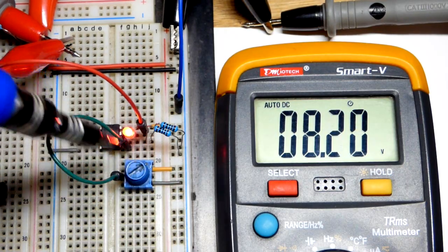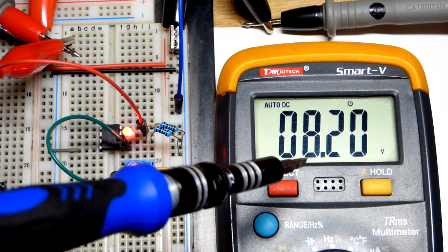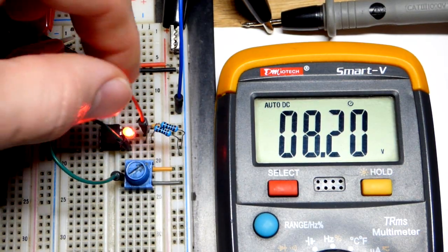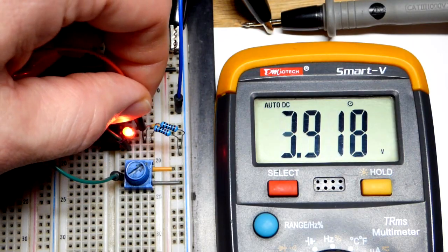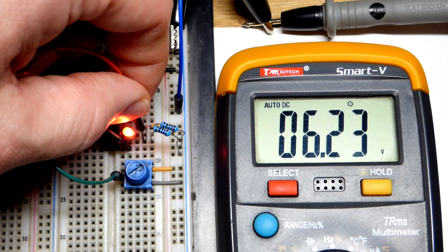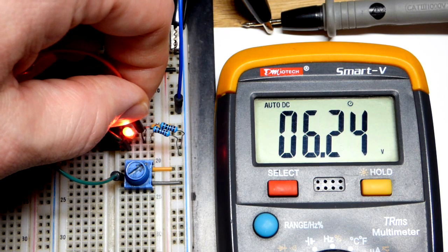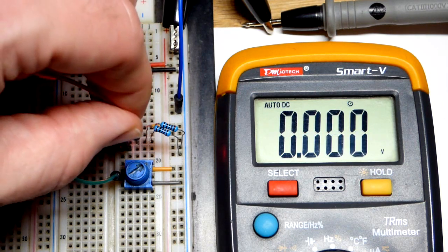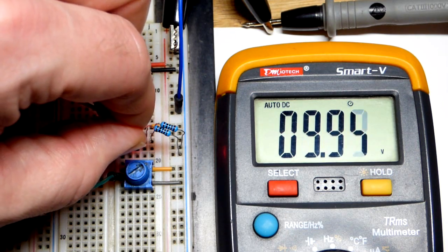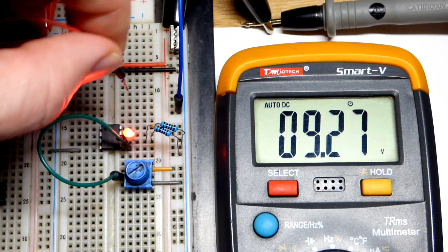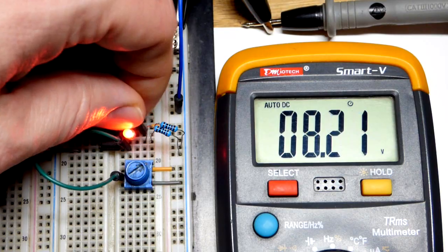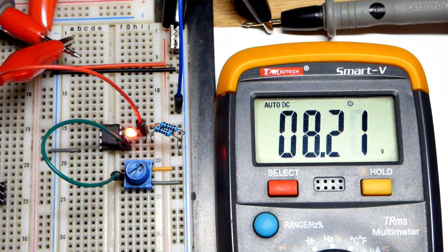But the output with the 10 milliamps current looks like it's limited to 8.2 volts. So this is going to be about 6.2 approximately. It may vary a little bit at the inverting input. That's not the same as the non-inverting input, the plus right there. So we're giving about 10 volts with the trim pot, but we hit that limit of the output right there, about 8.2 volts.